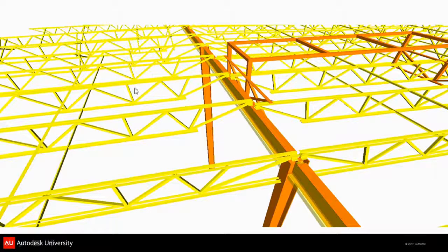So you really need this model that has the actual web profiles, the bridging, and if you have heavy chilled water piping, they actually need to know where your hangers are going to go. I'm talking if you've got larger bore piping with notable weight. If it's over a few hundred pounds per hanger, they actually have to have these panel points connect at the hanger locations, and the manufacturer needs to design those in. So most of your plumbing and piping, not a problem, but be thinking about how you're going to work with the other individuals. But you don't need all their miscellaneous connector plates that go all the way to LOD 400.